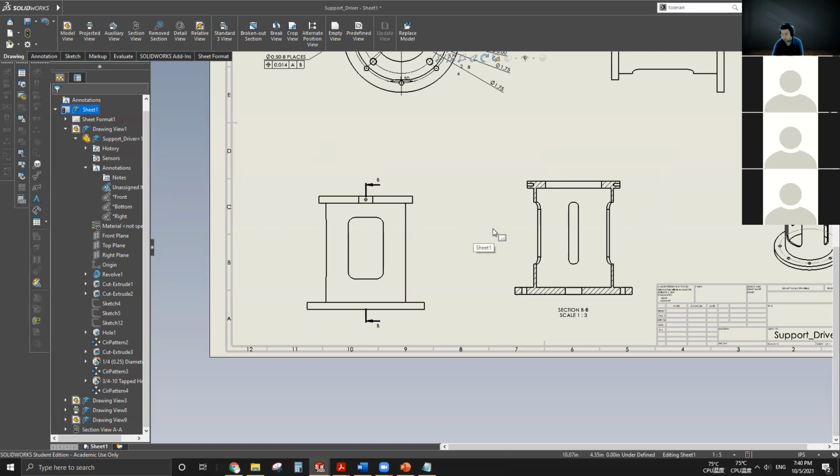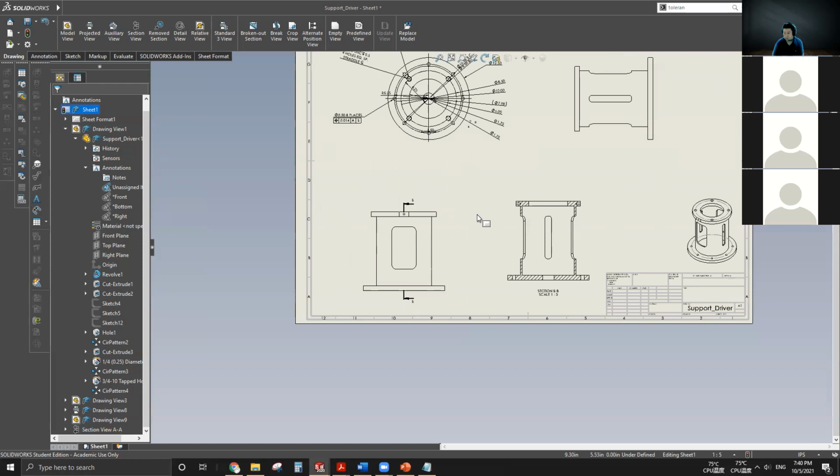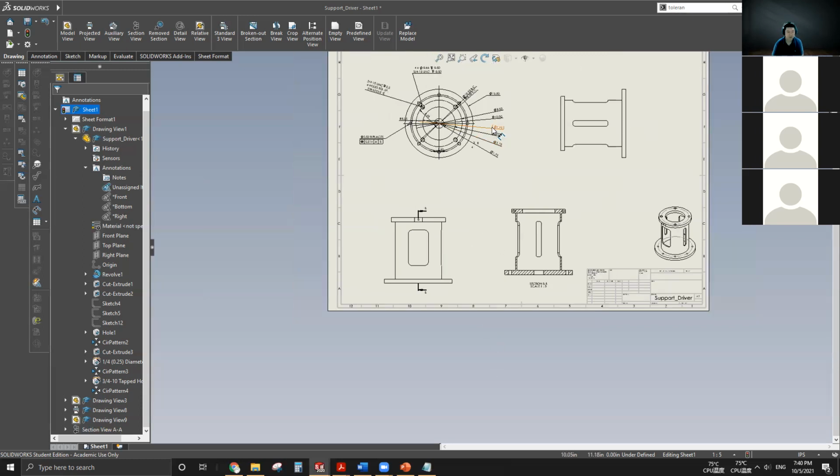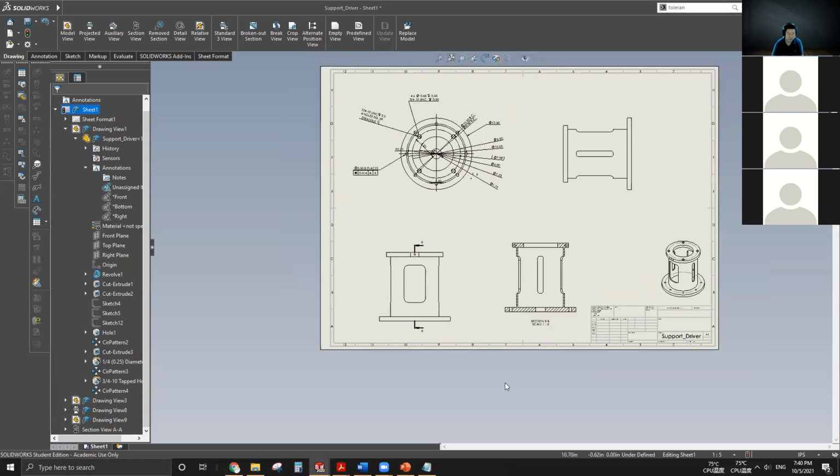And me personally, I never need to calculate the true positioning tolerance. I just use what has been used because the drawing needs to follow a certain standard, right? So you can definitely use that, or you can make it up. It's totally up to you. This is not about how precisely you can make this drawing correctly. It's just to give you a sense of what needs to go on there.